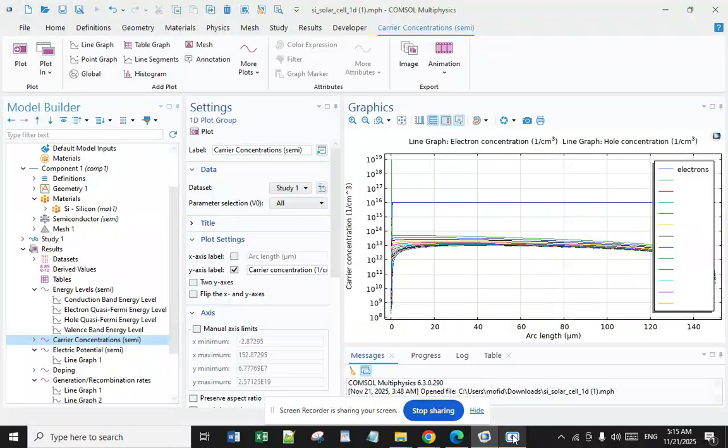And what about the rear contact designs? The first step is placement. Both positive and negative contacts are placed on the rear surface of the solar cell. The pro is that it eliminates shading losses on the front, allowing more sunlight to reach the silicon and be converted to electricity. And the disadvantage is that it requires more complex manufacturing processes to pattern the contacts on the rear side.